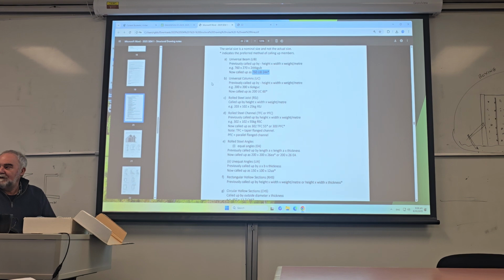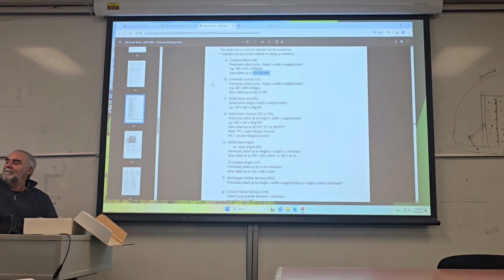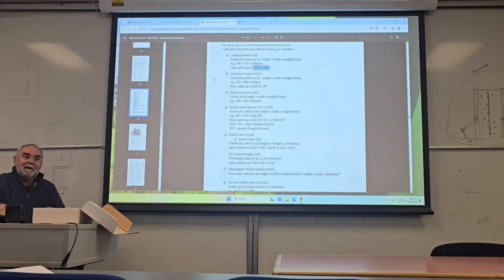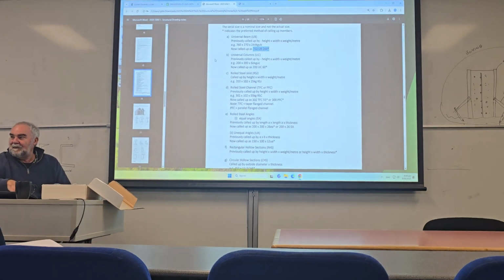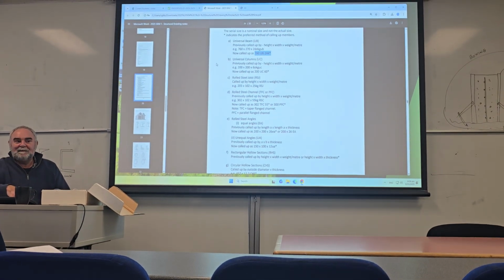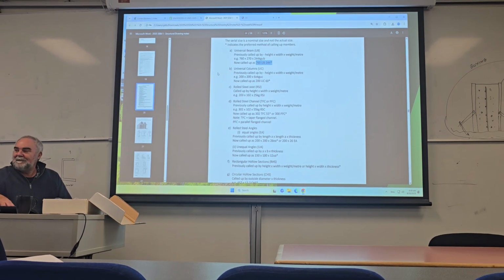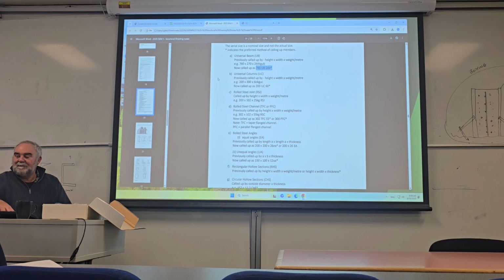That's easy, you're just using those call-ups, the new call-ups. But once you're adding on, say you're adding on to this building, you wouldn't just go, oh yeah, we'll just start drawing something on out here. If you're connecting to a building, you need to know what's there, so you need to go to council and get the old plans out. And the old plans will have those old call-ups. And you've got to understand what the old call-up means, so you can convert it for your new drawing into the new call-up. Some of them are very different, some of them are fairly similar.